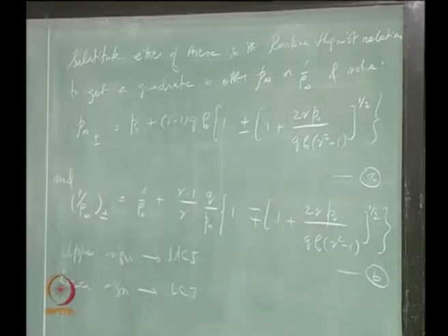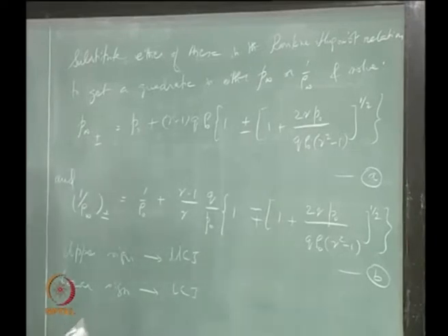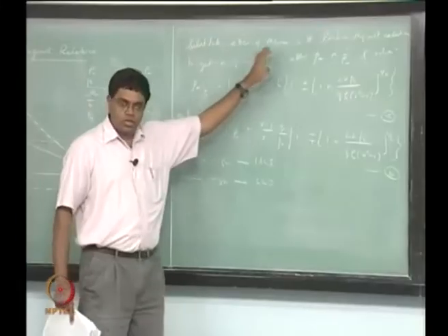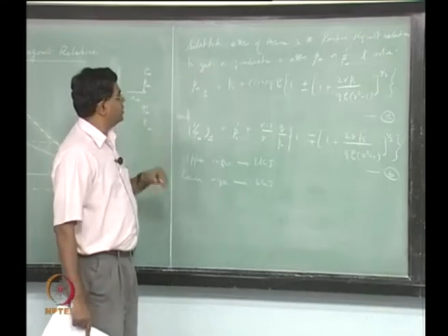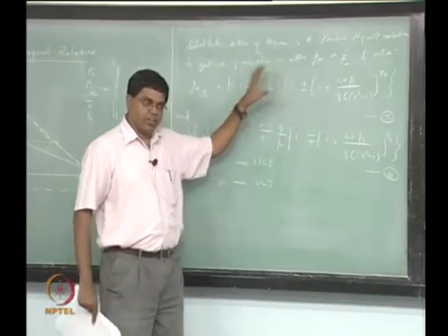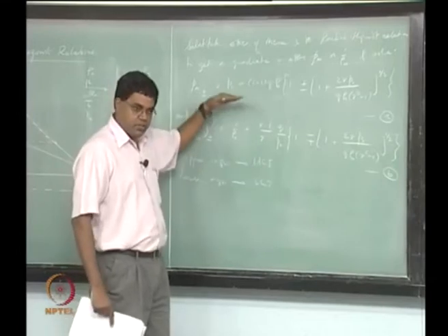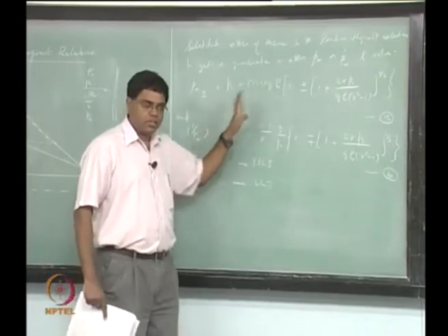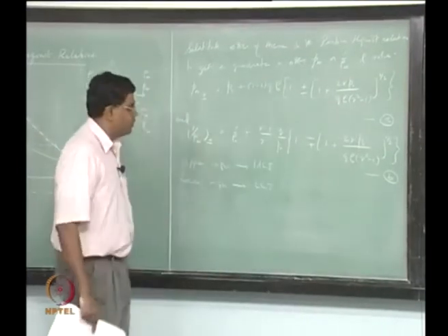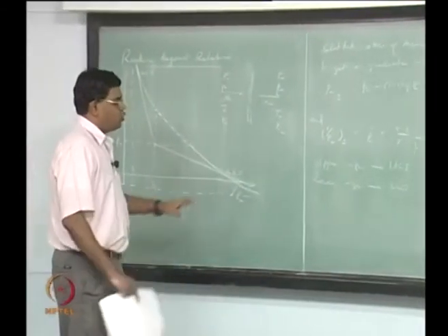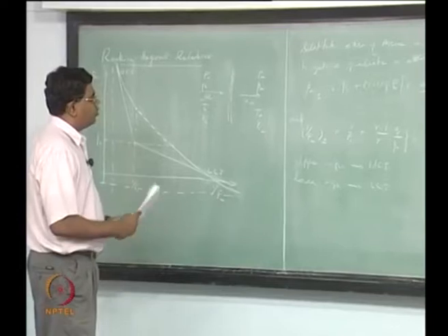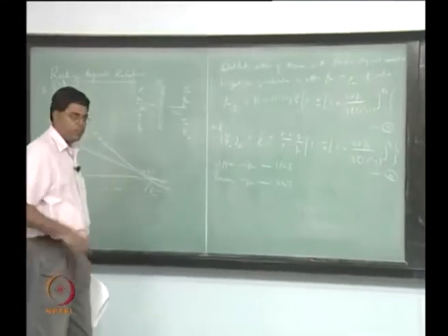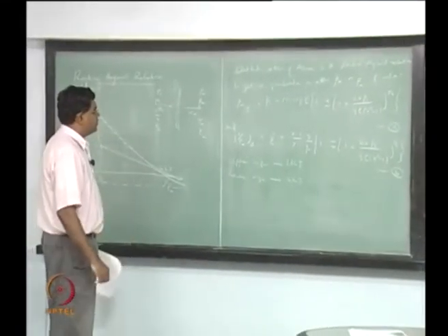In fact, to get this particular thing, substitute those two expressions in the Hugoniot curve expression, the Rankine-Hugoniot relation, and get the quadratic and solve the quadratic to get these. This is actually done for each of those separately, right. You will sweat a little bit, it's going to take some amount of time doing all this stuff, okay. It could be a bit boring, but you wade through the mathematics to see how the terms basically get grouped the way they are, okay, and then it's going to be pretty instructive for us because of what we're going to do next.